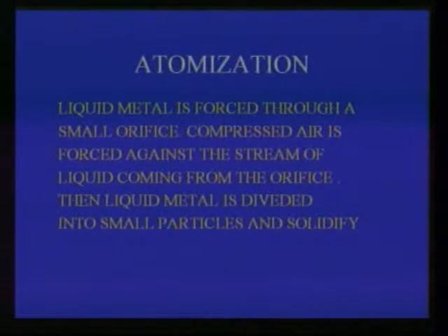In the atomization process, the liquid metal is forced through a small orifice. Then compressed air is forced against the stream of liquid coming from the orifice. Then the liquid metal is divided into small particles and gets solidified.